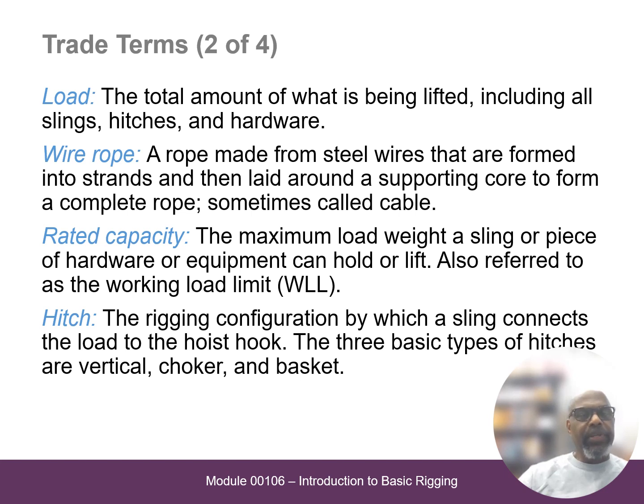So when we're lifting a load, we have to consider everything, not just the items you're trying to lift, but if there are turnbuckles and hoists and all those other things that are going to be supported, they need to be considered part of the load. If it has weight, it is part of the load.